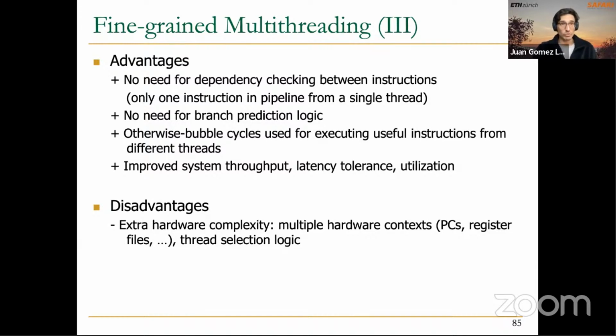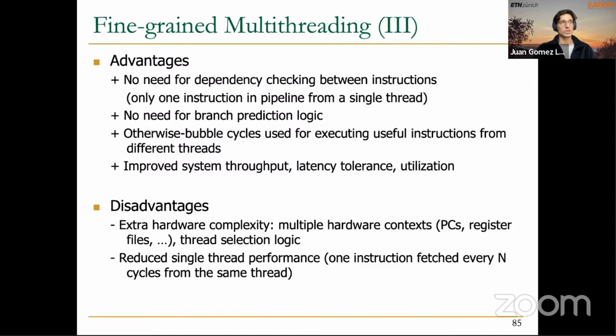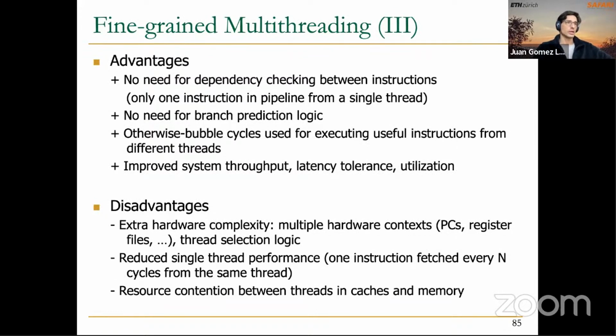The disadvantages are that the hardware is more complex, of course. You need more resources like PCs, register files, thread selection logic, etc. In principle, single thread performance might also be lower than in a system that doesn't implement fine-grained multithreading, and there might be resource contention. Why?